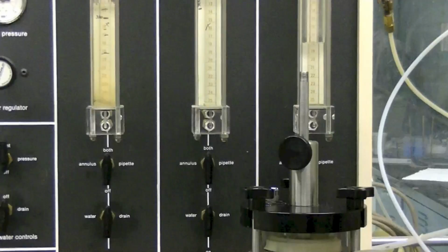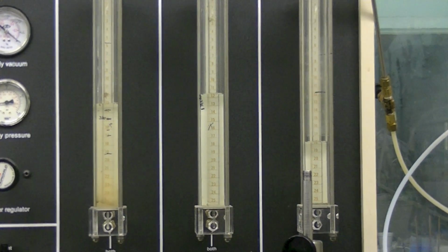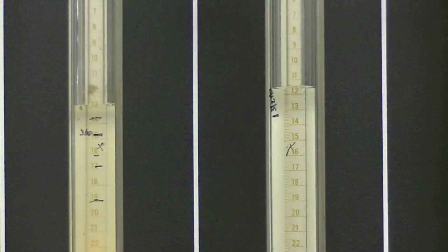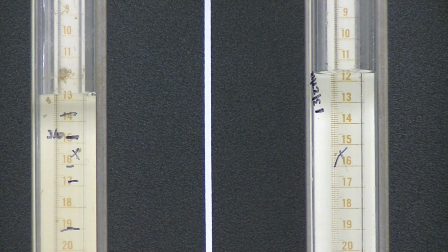The water level slightly rises in regulator 1, indicating void expulsion through confining stress. Allow for the hydraulic head to equilibrate in regulator 1. Once the head is stable, the sample has finished consolidating under that confining stress. Notice that the water level in regulator 1 has stabilized at 13.2.